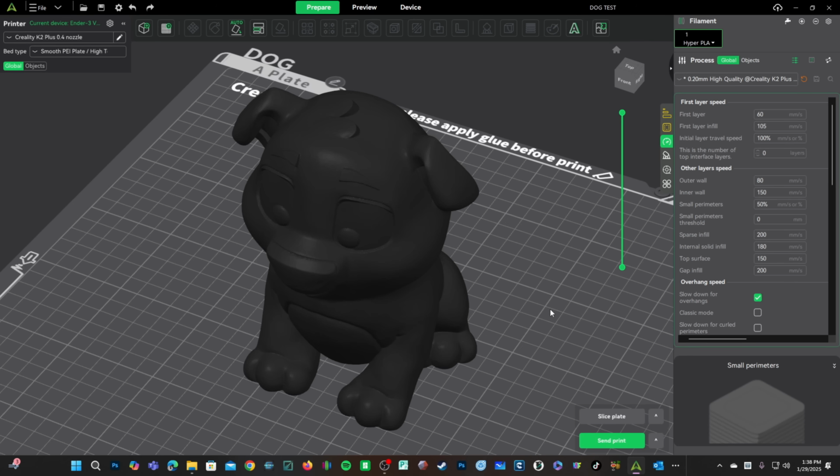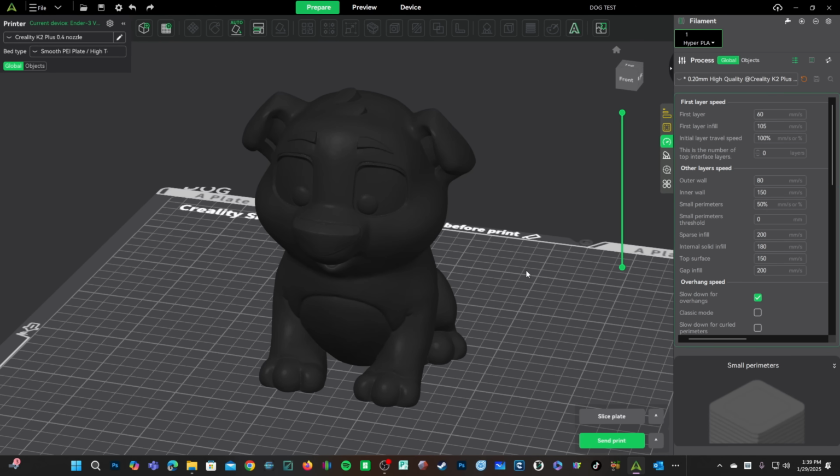The faster all of this happens, the lower your chance of success, the greater your chance of an extruder jam, of a poorly printed layer, of your model being knocked off the print bed, and a plethora of other potential failures. Be reasonable with speeds. It will protect you from wearing out or damaging your printer, as well as from having too many failed prints.